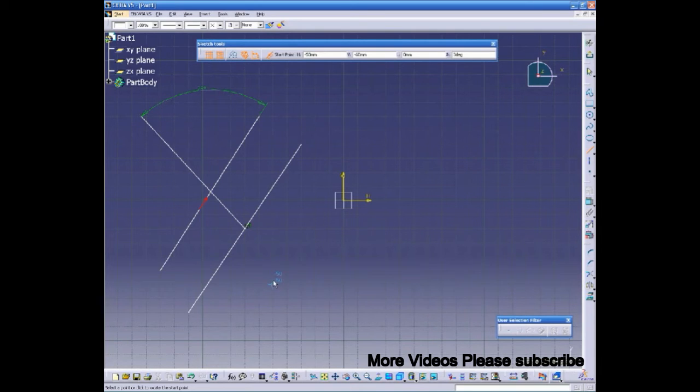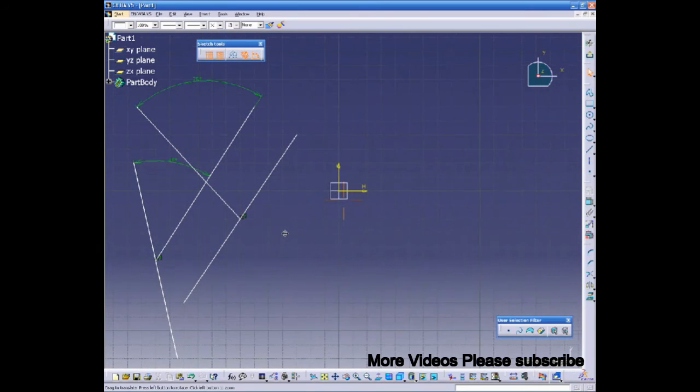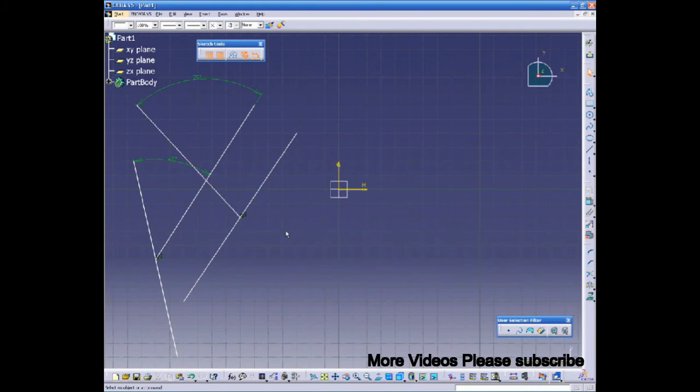Now, type in the angle field 45 degrees and press Enter. Click to define the starting point and drag the cursor to pick the ending location. As you see, the median appears. It is referenced with 45 degree with respect to the selected line.